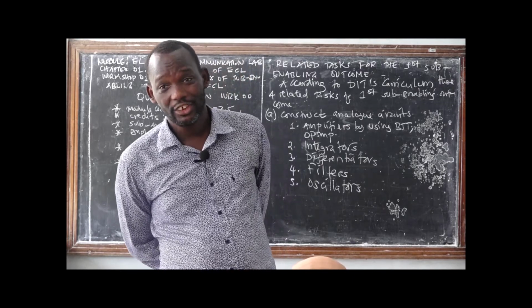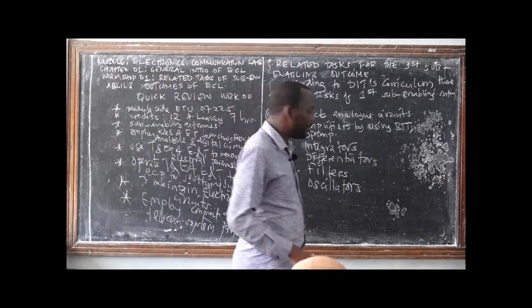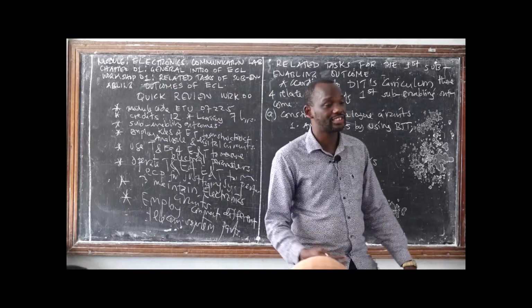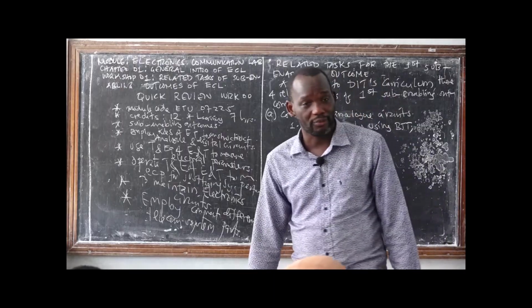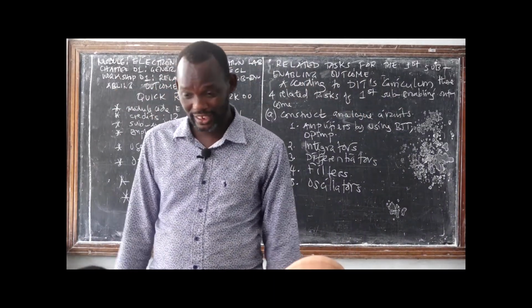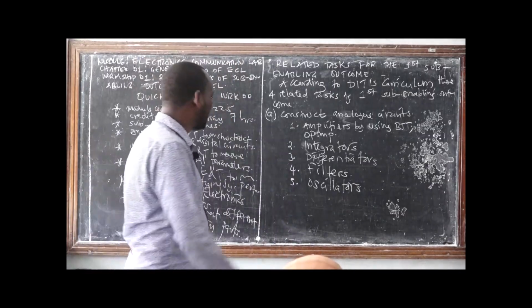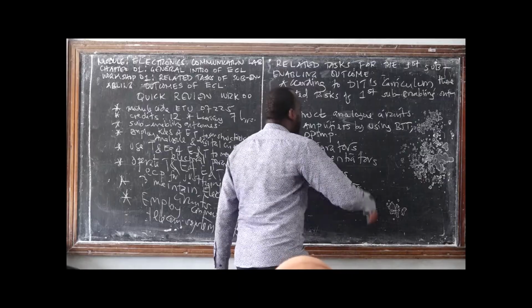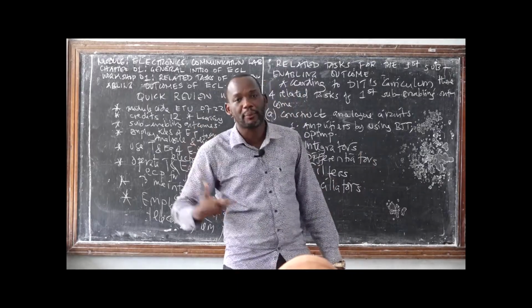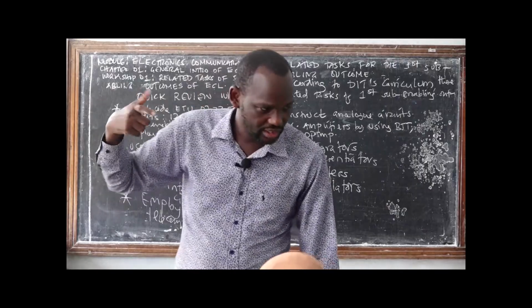Are we together? So it depends on the nature of the question you've been asked. You may say no, but then the question comes, how can we make an operational amplifier? Oh, we are using bipolar junction transistors. So then, why are you saying that we cannot construct it? Simply, the meaning of the question is that we cannot use the discrete bipolar junction transistor to make integrators and differentiators.